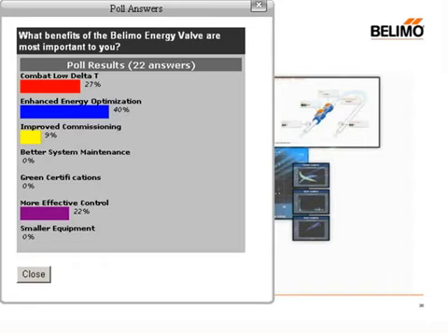So I don't see that as a real condition you're going to run into, unless you push the delta T too high, and we're not recommending it go any higher than the design for that zone. We're just asking the system to operate as it was designed to operate.